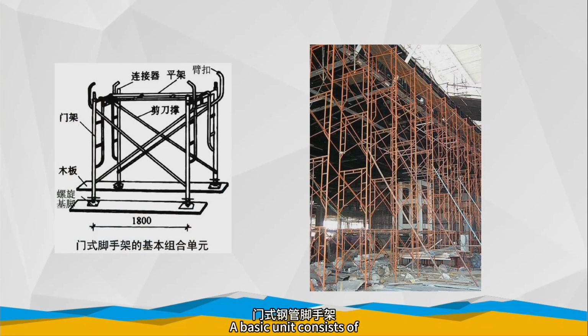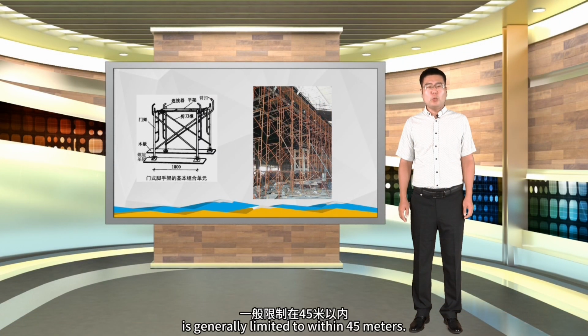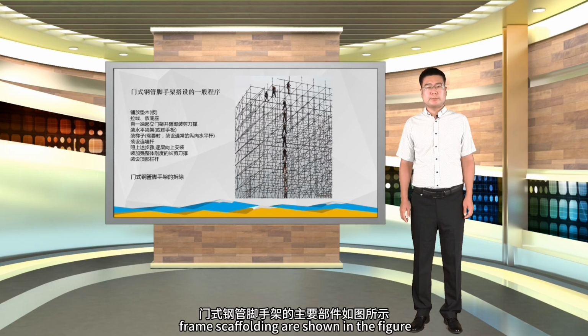A basic unit consists of portal frames, cross braces, and transoms or scaffold planks. Connect the basic units to form the whole scaffolding. The working height of steel fabricated frame scaffolding is generally limited to within 45 meters. The main components of steel fabricated frame scaffolding are shown in the figure.